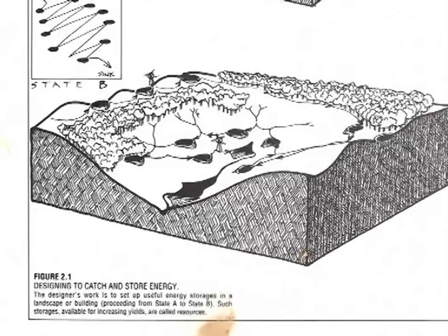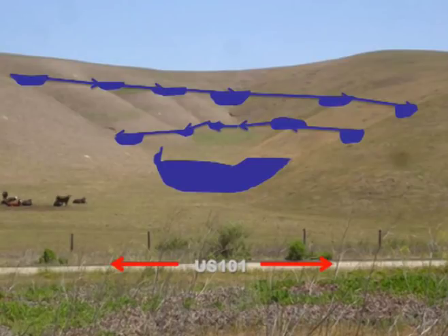Exactly that. You watch this water try to come down, and it goes dam to dam, and eventually makes it to the bottom and it goes away, or you put the pump on it and you pump it back up to the top of the hill. That's in the Permaculture Designer's Manual. So let's go back to that same picture, this one here, right? Now let's design it according to the book. This is exactly what he talked about, building a high water collection that goes to the next one, to the next one, to the next one. Then we'll let it sheet perfectly horizontal. It sheets down here, goes to the next one, makes a sheet, goes down.